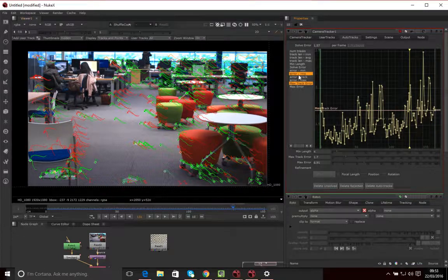Next thing I want to do is pick track points which, when it came to actually putting them into the 3D solve, didn't corroborate or didn't fit the solution of the other tracks. As I'm using this information to solve the camera in 3D, some tracking points fit the solution of the position of our camera better than others.